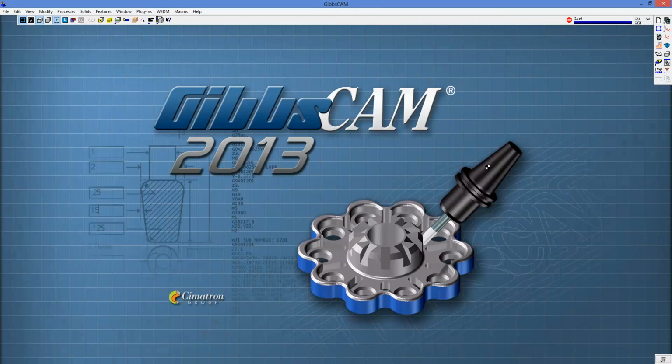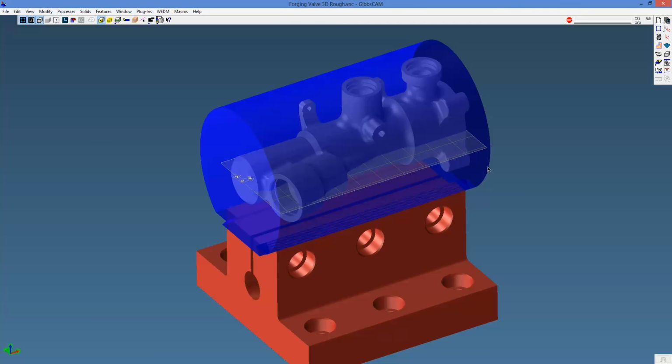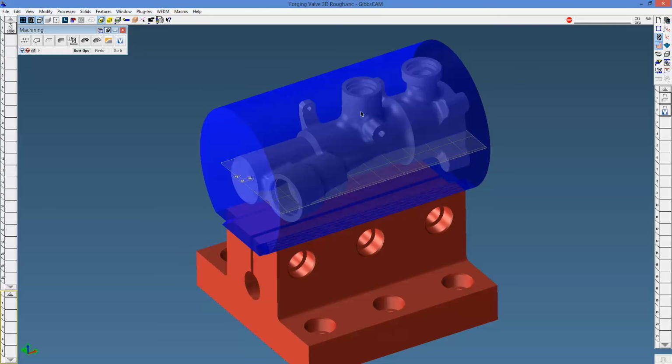And so far, in all the examples we've seen, it's been 2.5D, right? Straight pocket that doesn't change. In this particular example, you can see that we have a valve body enclosed in a semi-circular kind of stock there shown in blue, and we want to remove it that way. And again, I have both the traditional rough and the VoluMill here for comparison.